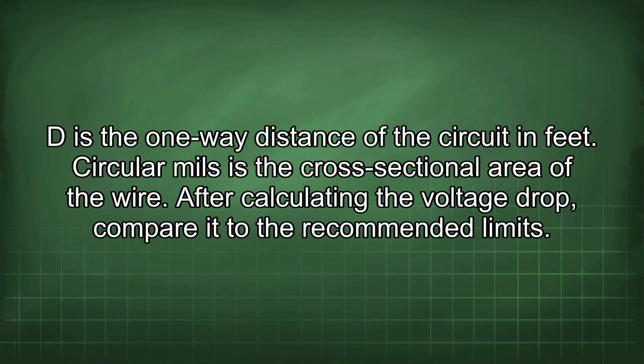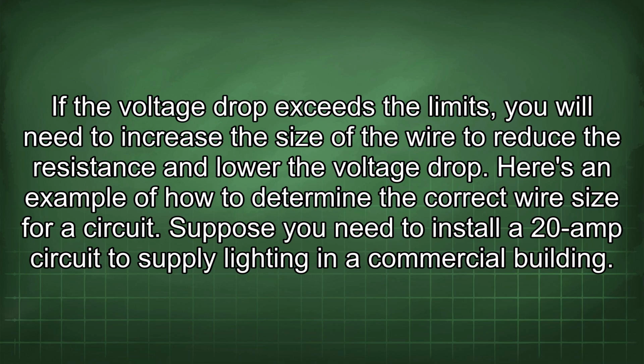After calculating the voltage drop, compare it to the recommended limits. If the voltage drop exceeds the limits, you will need to increase the size of the wire to reduce the resistance and lower the voltage drop. Here's an example of how to determine the correct wire size for a circuit.